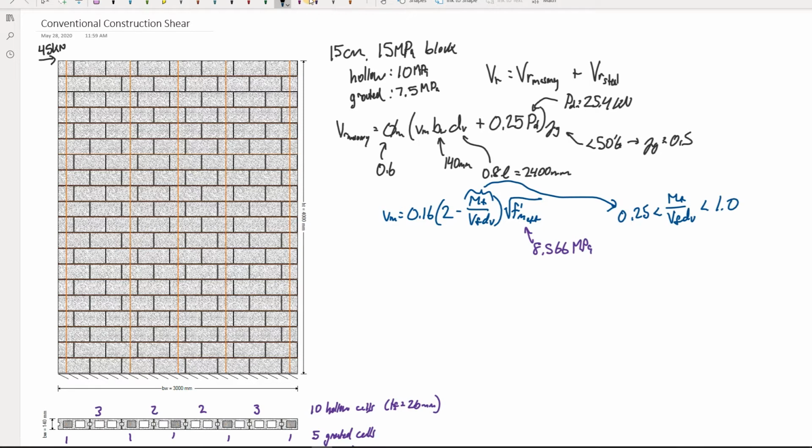So this is a value that actually varies along the height of our structure. If you recall, we have a lateral load being applied at the top, and so we have no moment at the top. At the very top of this right here, M equals 0. But then at the bottom, it goes all the way up to the moment, which is equal to V times our height.